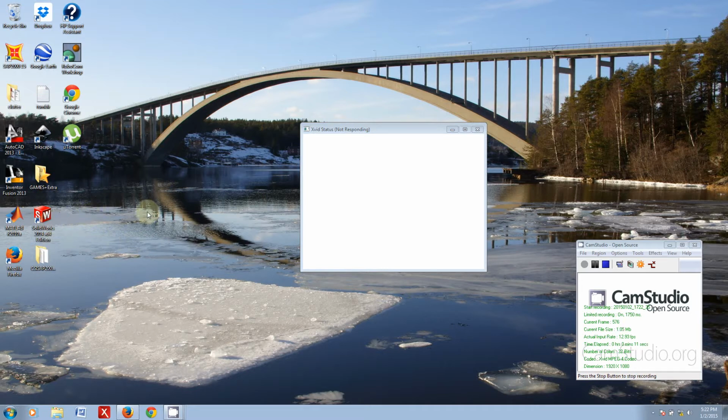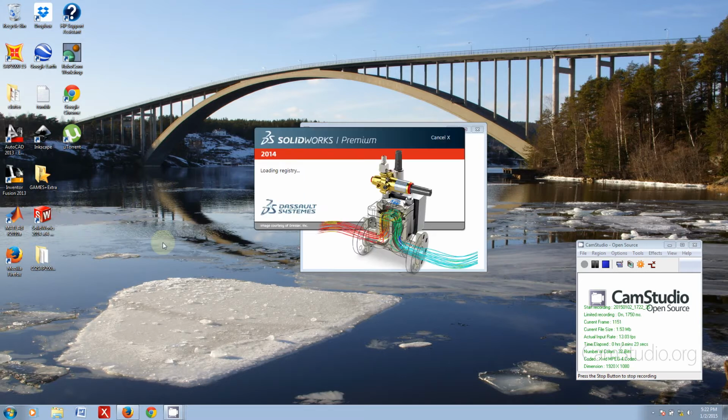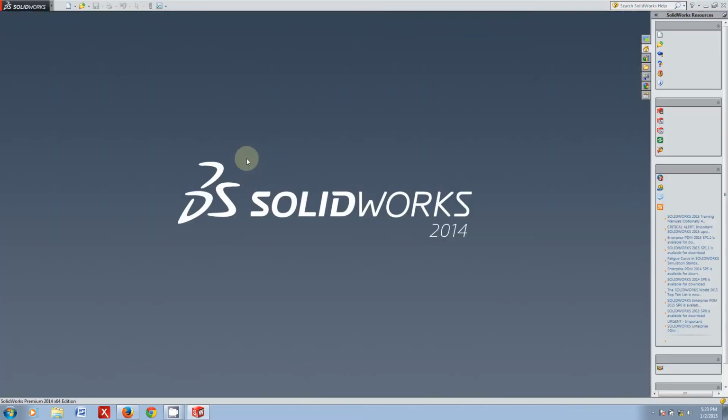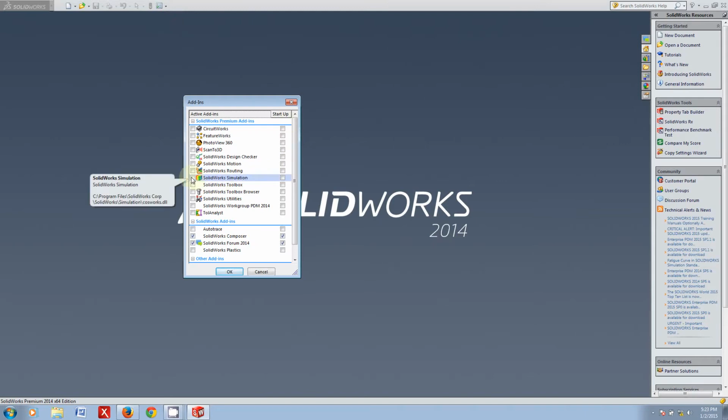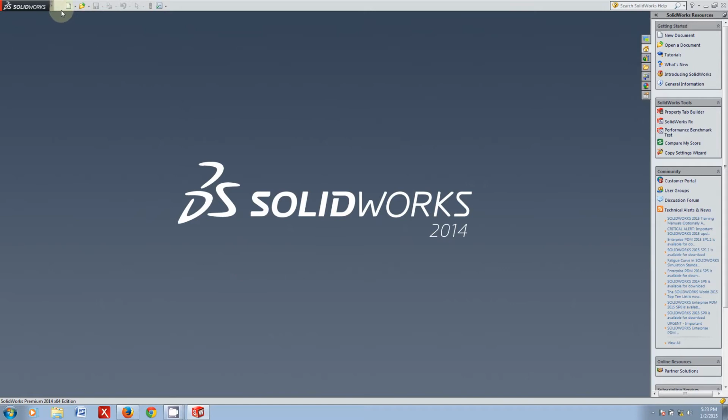So, suffice it to say, you have SolidWorks. I'm just going to begin from this point. If you need SolidWorks, please contact me and I can step you through the process. So, SolidWorks, let's go ahead and open it up. Basically, you're going to want both the base SolidWorks and SolidWorks Simulation. To activate SolidWorks Simulation, you have to go to Options, Add-ins, and make sure you have the SolidWorks Simulation box checked. Click OK, and now we're going to use some of those parts from our previous lesson.